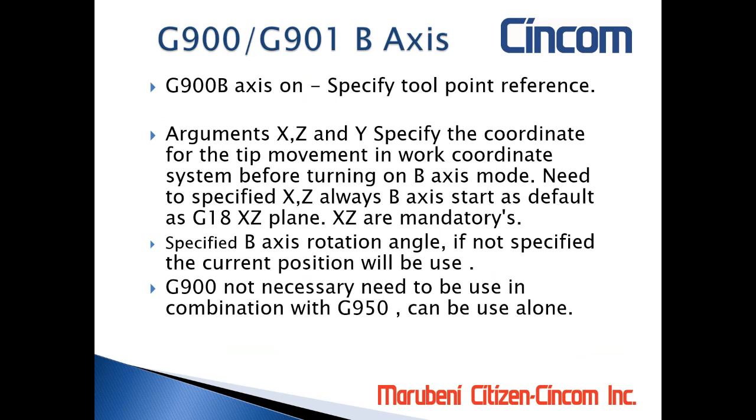If you set the tool as a diameter, pretty much all the time we have some number in diameter. I know people, and I will say some practices, that try to keep it at zero. That's okay, but many times you need to have some tools stick out more than another one, so then you're going to end up having some numbers in diameter. And we recommend to set B-axis as cross.